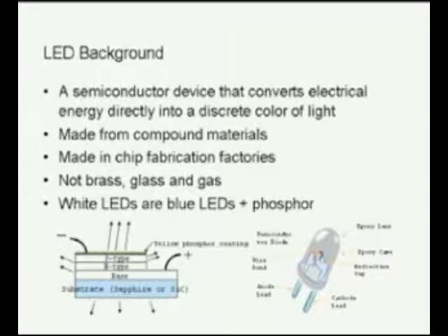This forms an encapsulation around the LED, which consists of not just the die itself, but the wire bond, the reflector cup, and so forth. All of these combine to produce a complete package, and electricity can be put into the leads and go through the wire bond into the LED die and then emit light.